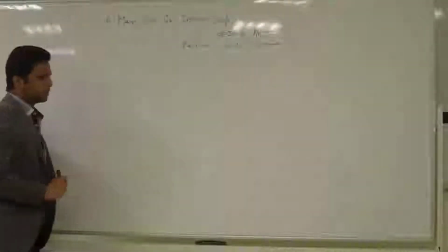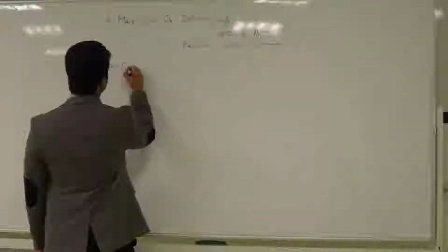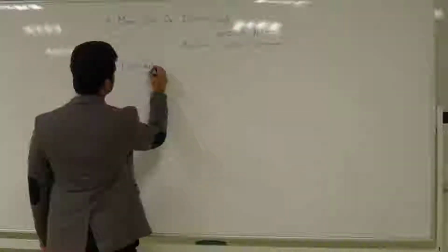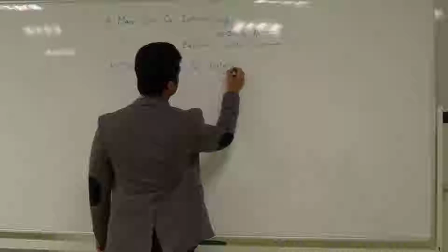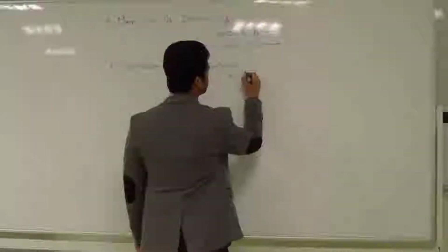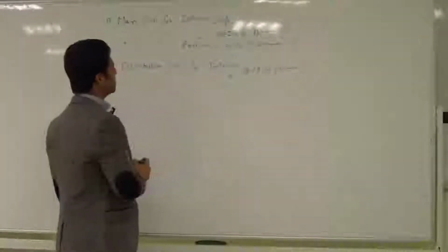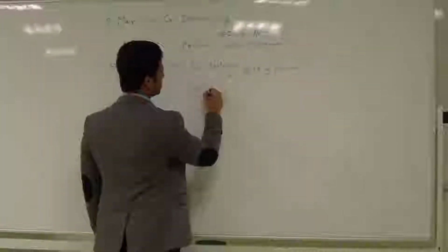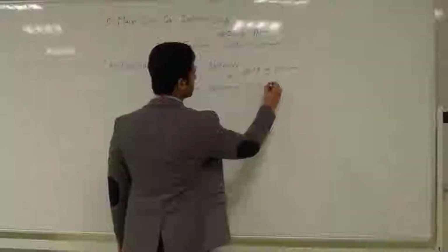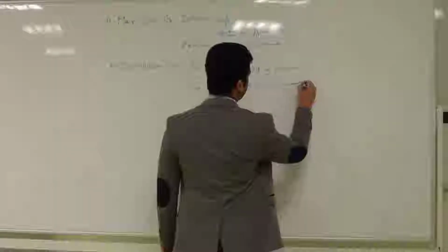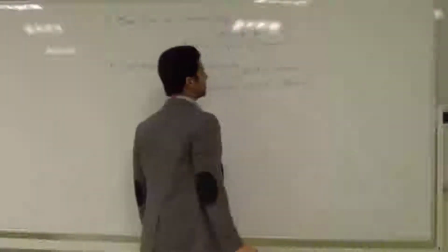Next is the distribution steel. For interior, it is number 13 at 190 spacing. Distribution steel for interior: 190, number 13. And what about the distribution steel for exterior? Number 13 at 256. Okay, round it down to a multiple of 10, so 250. And what other steel?